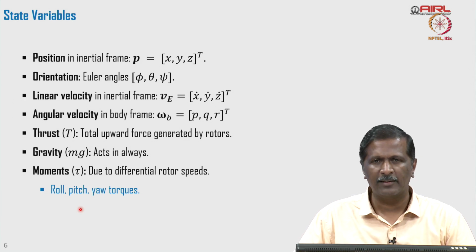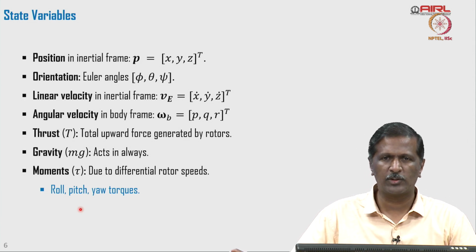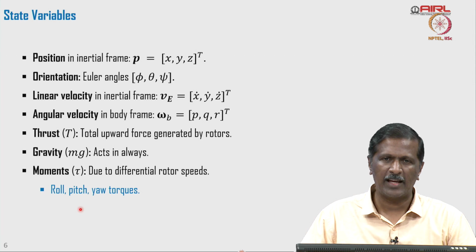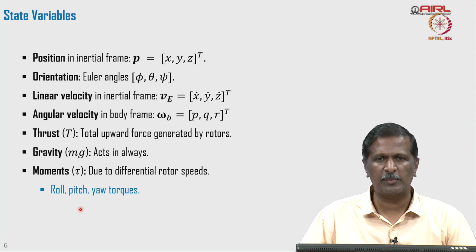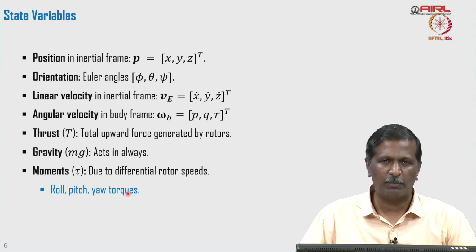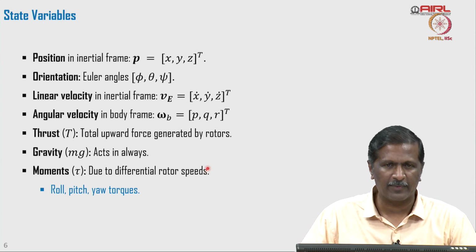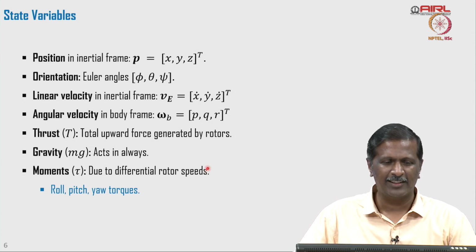I have to mimic the external environment and how it is going to affect the response. Those environment effects also have to be added, so that the response from the model and the response from the real aircraft are as close as possible, so that we can validate our control and our navigation algorithms before deploying them in the actual field.